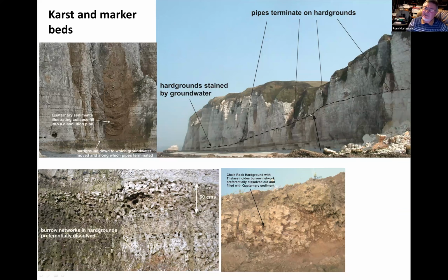So this surface is controlling the depth to which karst has developed within this ground. So here they're coming down to relatively shallow depth. Here they're coming down to depths greater than 90 meters. So you've got a huge difference in the depth to which your dissolution features have gone, and it's been controlled by that hard ground surface.